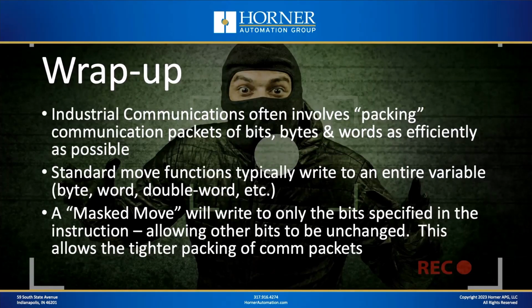You know, byte, word, double word, whatever it happens to be, they're writing to that entire destination. Whereas a masked move will only write to the bits that you specify in the instruction, allowing the other bits to be unchanged. So this can perform what you're looking to perform without accidentally overwriting data that you don't want to overwrite.